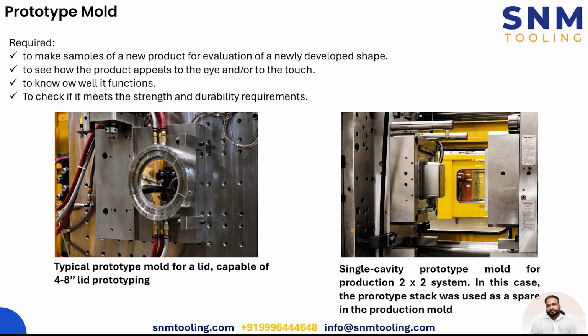Secondly, since productivity is not the question here, the cooling is not time limited. So there is no such requirement of adding cooling channels, which will further reduce the cost of the mold, right? And thirdly, the material can be either mild steel or aluminum, right? So long as they are meeting the expectations, or strong enough against the heat and pressure of the molten plastic, they will be able to bear that, right?